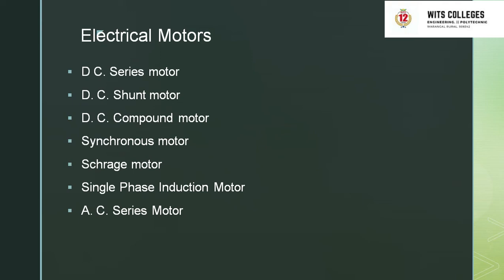So those are the motors. Next, in the past, induction and synchronous motors were employed mainly in constant speed drives, whereas for variable speed drives, these machines were either too expensive or had poor efficiency. Consequently, variable speed drive applications were dominated by the DC motors. That's the reason AC motors are now employed in variable speed drives by using different types of semiconductors like thyristors, power transistors, IGBTs and GTOs.